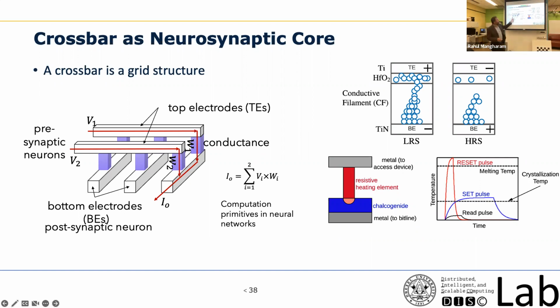All these weights can be any exotic materials like phase change memory and memristors. These are novel materials that you can use to build this transconductance, so that current can flow through them and multiply. So you don't have any CMOS components anymore. Of course, CMOS is there to build your neurons, but the synaptic weights are all in exotic memories like this.